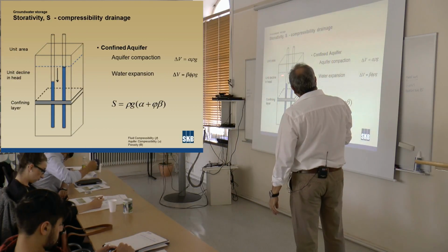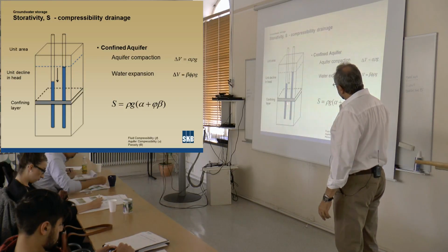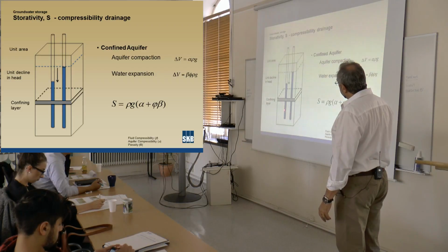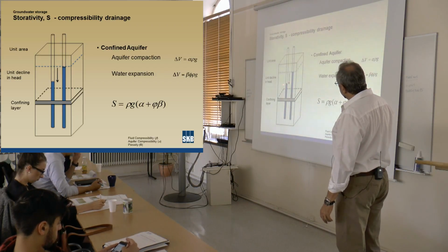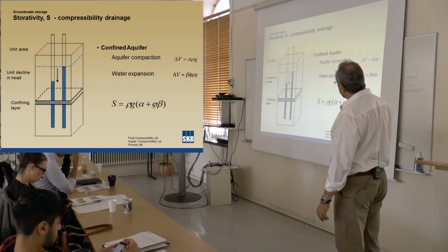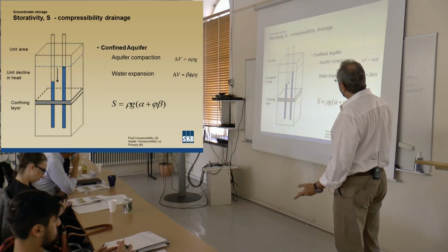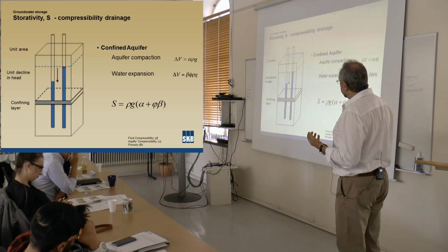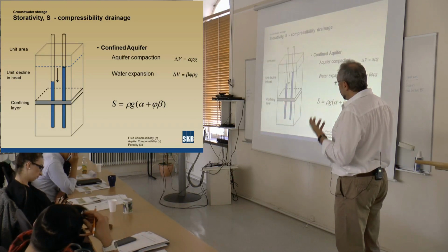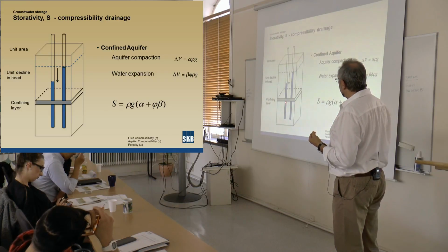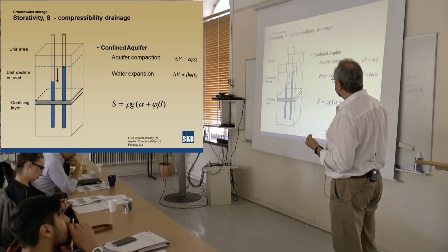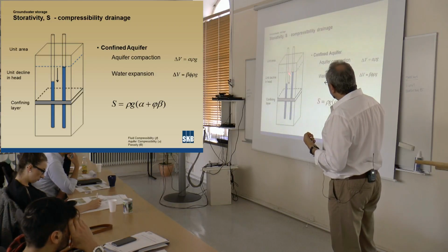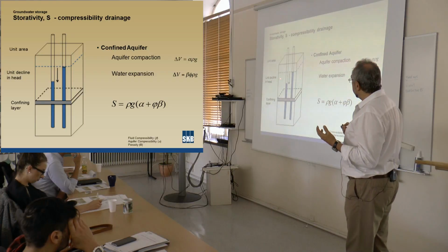we have two boreholes open in this lower aquifer. So this is an upper aquifer and this is a lower aquifer, and they are isolated from each other through this confining layer. So this means that it is under pressure, and when we insert a borehole, we will have a pressure rise up to this level. Okay. For a unit decline in head, the definition is the same here.